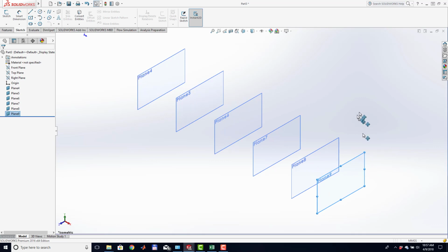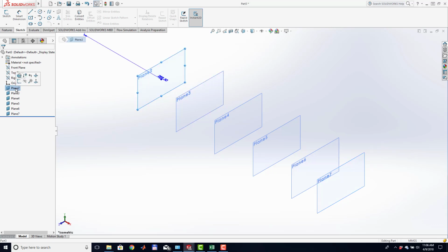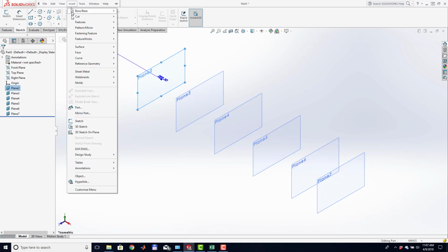And we can see that these reference geometries will in fact represent the stations of the propeller, and we have data that represents these stations that comes from the Sensenich repair manual. What we need to do now is to import the curves which would represent the camber of our airfoils at the varying stations of the propeller blade. So I'm going to do insert, curve through XYZ points.